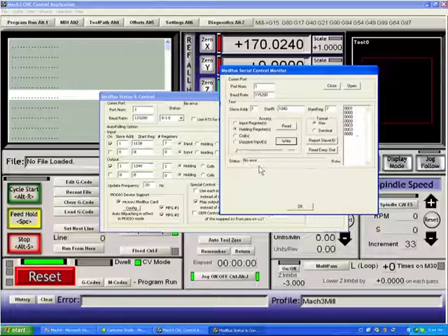The status bar here will tell you if you're having a problem connecting to it or if you're trying to read an address that the ModBus device won't allow you to read. So when you're trying to get a ModBus device operating, to test your memory addresses and to test the way that you're controlling it, this is a great screen to use. For example, if you had a DL5 and it has an LED on bit 3, you could come into this device, put in a 4 hex, hit write, and the LED on the ModBus device would then light up. So the ModBus test dialog is very important to you when you're trying to set up an unknown ModBus device.